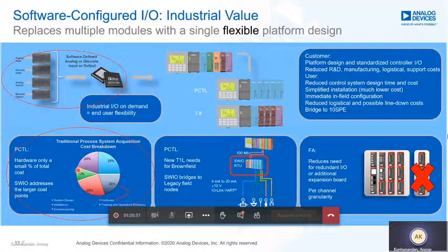And when it comes to the commissioning, with SWIO points in place, you really don't have to add points as and when required. Based on the future requirement, you can have some points already in place when the commissioning happens, and in the future you just configure it for whichever inputs you want. So basically, the SWIO concept brings in a high level of operational efficiency. Hence, you save cost when you go for this kind of concept, and this holds good for factory automation, process control, all those segments.